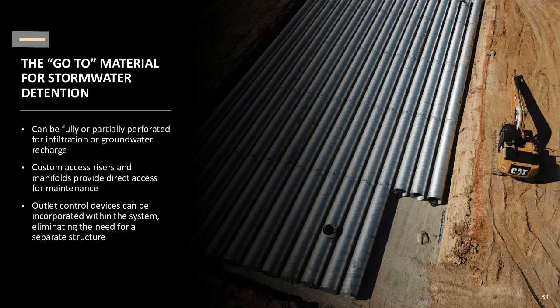Fabrications are no problem whatsoever for corrugated steel pipe. The ability to cut and fabricate allows you to have inline risers, Ys, Ts, manifolds, and bulkheads. So just about any fabrication need you would have on a site can be accommodated and custom built specifically for your location, to minimize the amount of other structures that have to be constructed in order to utilize one of these systems. You can have integrated risers to eliminate concrete manholes, with the advantage of faster installation as well as decreased cost.